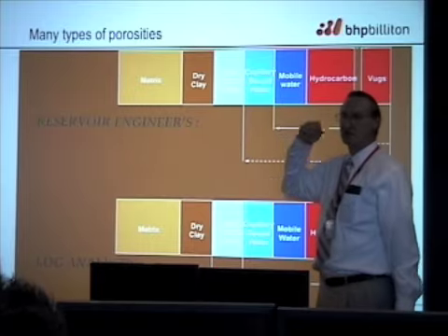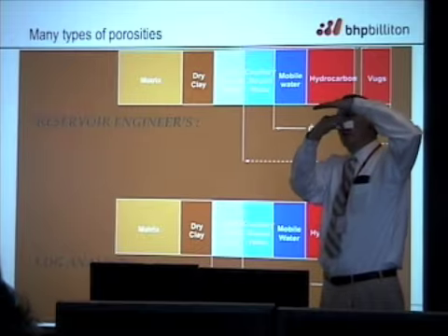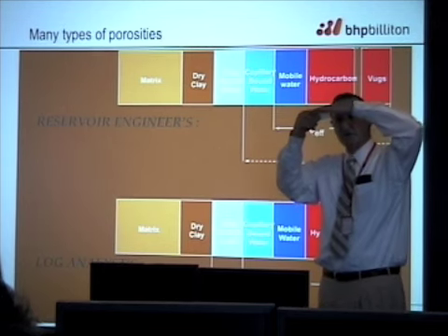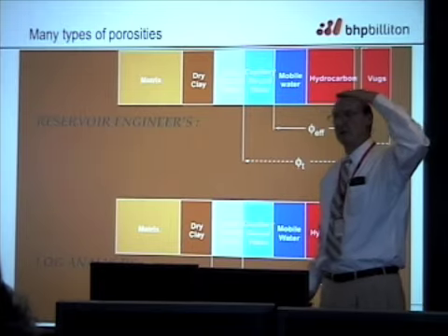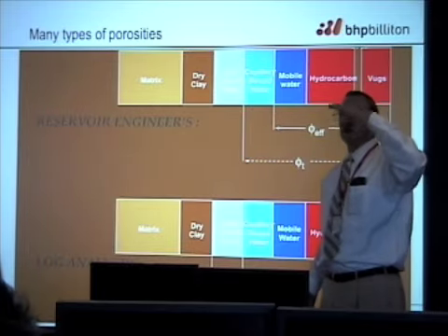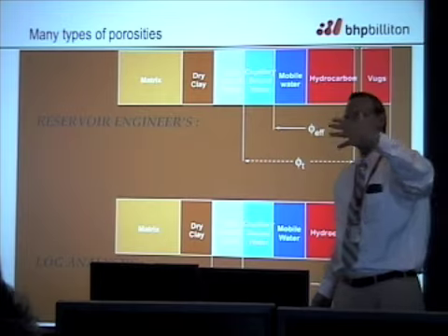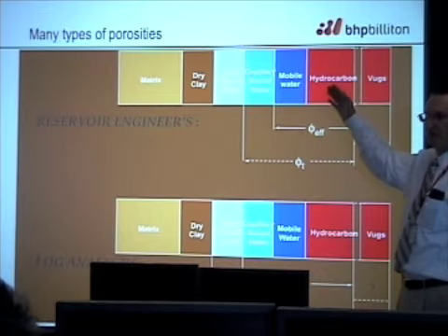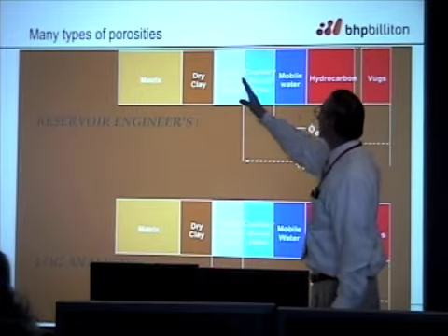If you look at the microstructure of clays, the clay minerals have electrostatic charges on them, and in between those clay mineral layers that have electrostatic charges, there is water, bound water. It's very tightly bound in the clay minerals, and it's very hard to get it out. Stress over a long period of time, enough stress, can remove a monolayer of water. Usually there's one left at the end of that kind of process, but it's very tightly bound, and that's what they're talking about here when they talk about clay-bound water.